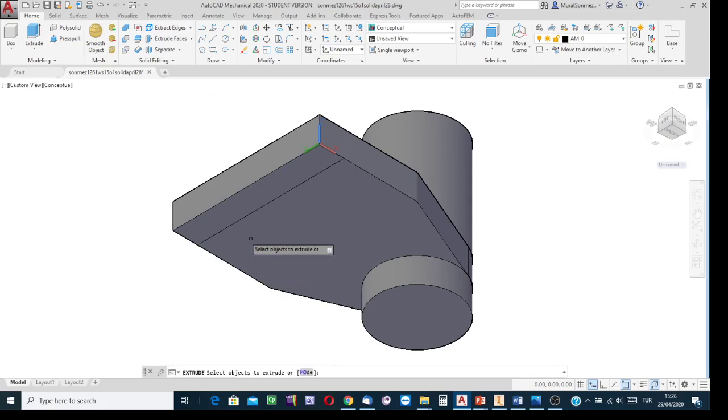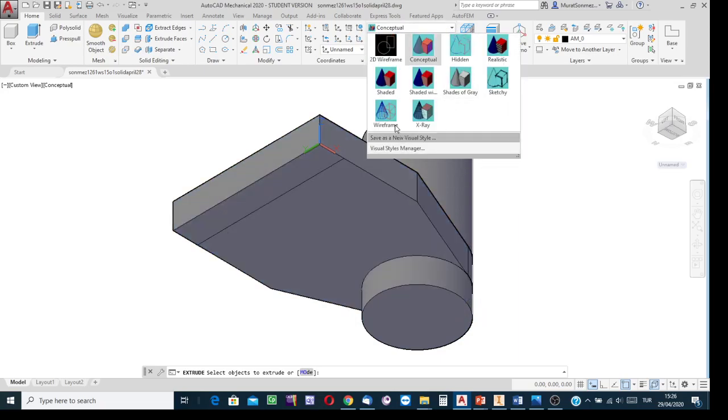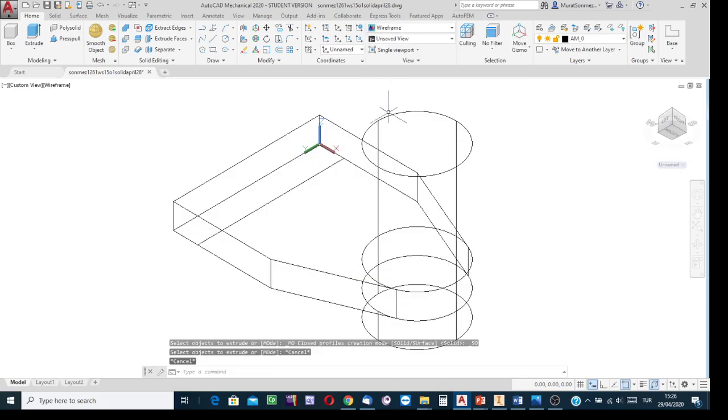Apply the extrusion process. Be able to indicate the rectangle. If you're in difficulty while trying to indicate the area bounded by that rectangle, but over the surface some other regions are being highlighted, then you know the shooting method. Change the visualization style to wireframe. You can much more easily indicate it.